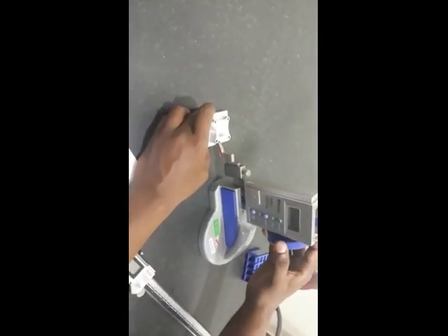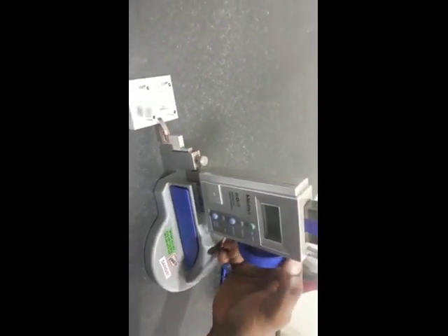So first of all, I'm just going to use height gauge to see this particular depth, which is 15 millimeters. So I'm going to check the height from this point all the way till this point. So how I'm going to do is I'm going to come here, I'm going to set to 0, so it's 0 at the moment, and I'm going to take it all the way up, and I'm going to take it right here.